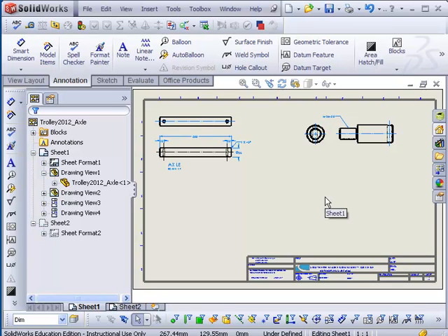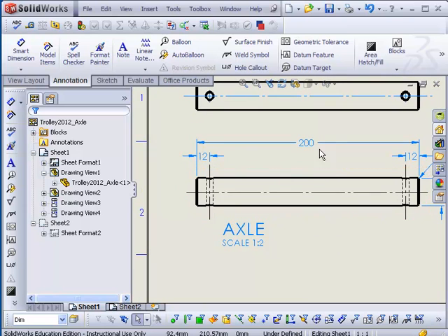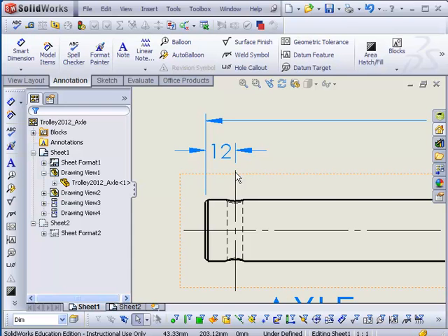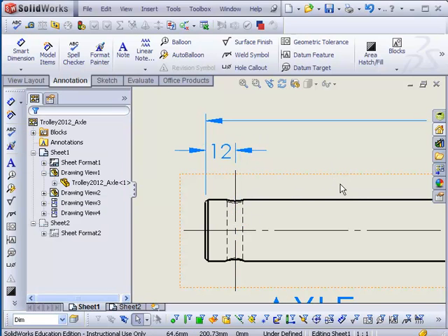Just make sure whatever you do, it's done correctly, and that means I'm going to look for proper dimension spacing, proper dimension style. Vertical dimensions are not going to be acceptable. They all have to be horizontal. I'll accept a couple places where the center line gap exists because it's just very difficult, again, in SolidWorks. Even if I bring that down like that, it just doesn't want to stick.